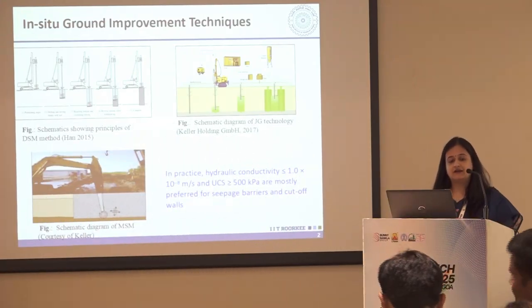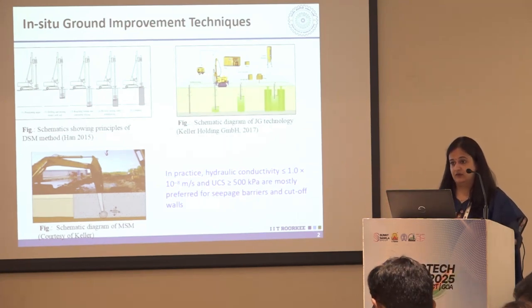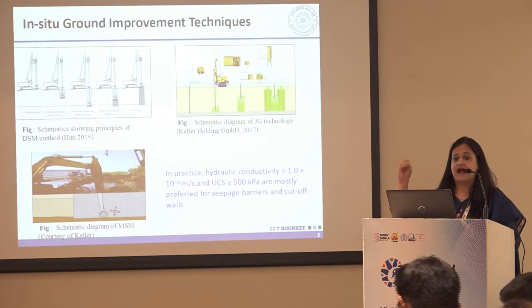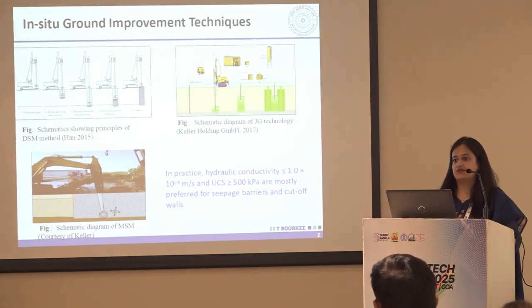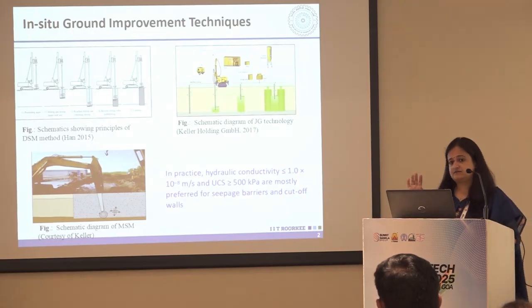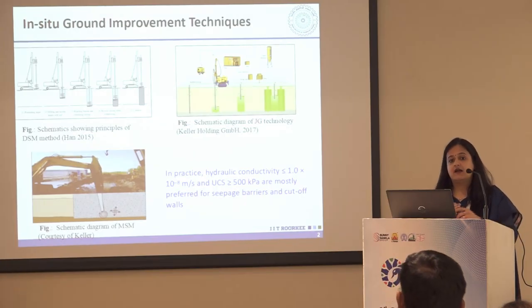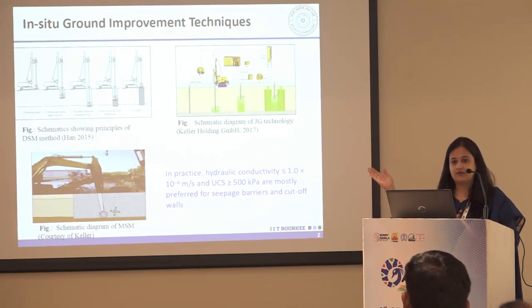Another technique is mass soil stabilization, wherein we are creating blocks of stabilized region. It is usually used for peaty soils or contaminated ponds, wherein we are adding lots of cement to these regions and making them reusable from a construction or stabilization point of view. Now the point here is that most countries, cold countries, Scandinavian countries, the USA, and South Asian countries, are using all of these methods. In India also, we have used jet grouting in the Teesta project, the NTPC coal dam project, and the Polavaram dam project.